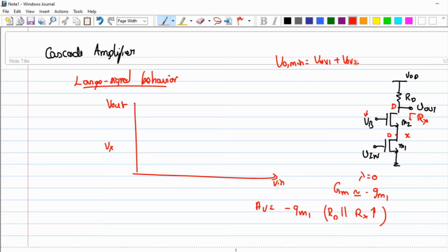I can use a MOS. We know that when I take a MOS transistor, basically the current has to flow. We also know the impedances that I see when I look across each of these points. When I look into the gate, it is infinity. When I look into the source, it is 1 by gm, an approximated value. When I look into the drain, it is r0. Now, which point could be fixed in order to have a very high gain, and also make sure that the currents are flowing through the device, through the terminals that you are choosing?